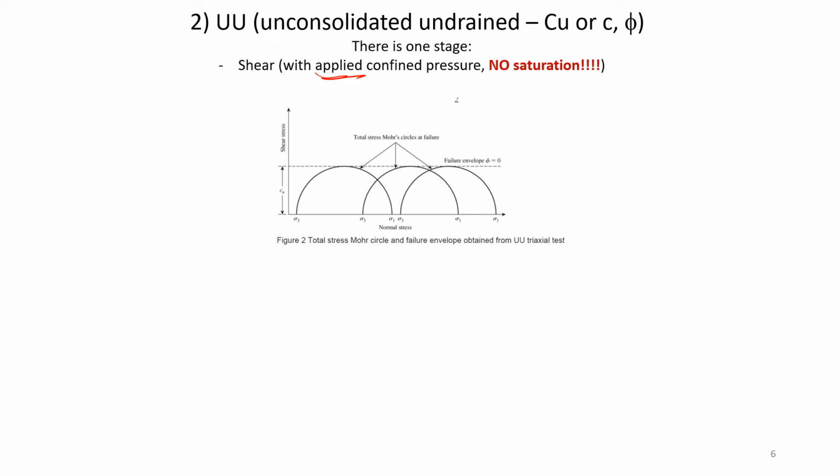UU test, unconsolidated undrained. Only one stage as well, but you have to apply confining pressure. But guys, just remember, no saturation. ASTM standards don't say to make any saturation. It's a very important point. We're going to discuss it later.